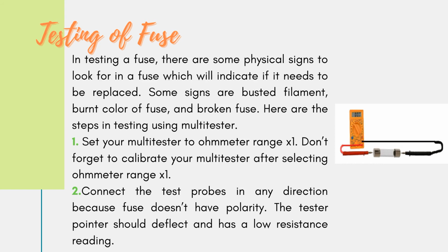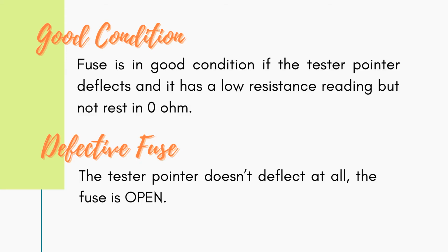2. Connect the test probes in any direction because fuse doesn't have polarity. The tester pointer should deflect and has a low resistance reading. Good condition. Fuse is in good condition if the tester pointer deflects and it has a low resistance reading but does not rest at 0 ohm. Defective fuse. If the tester pointer doesn't deflect at all, the fuse is open.